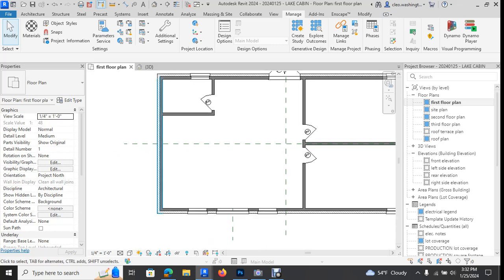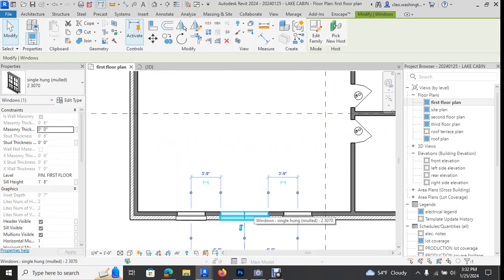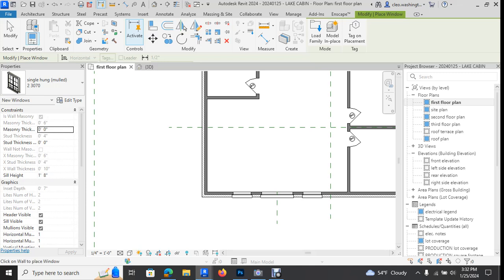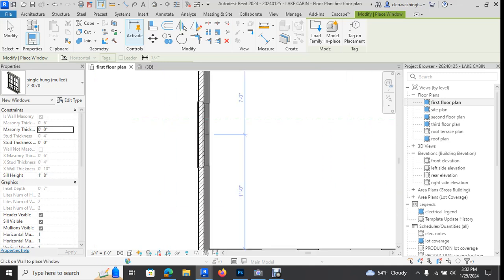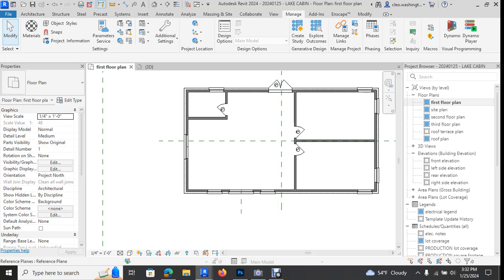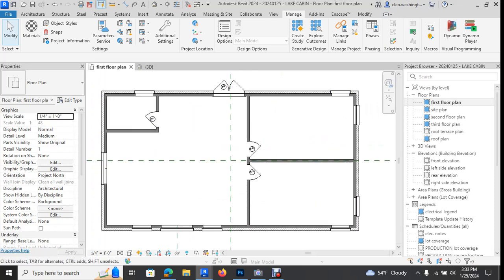So now let's go and add the windows on this side of the living room. We're going to take this same window, since we already have it constructed, right click, and click create similar. And this guy is not centered on the room. It's kind of more like right there. I like the fact that they're giving us a leeway. Typically, you'll have dimensions showing us exactly where each window is. And in fact, I think we need more windows in the bedroom.